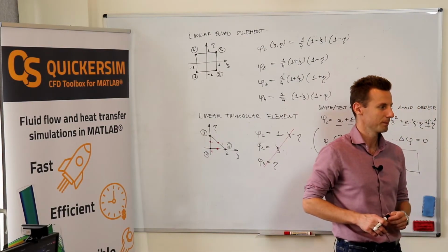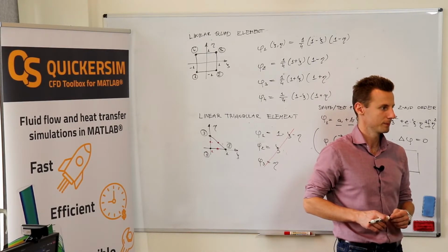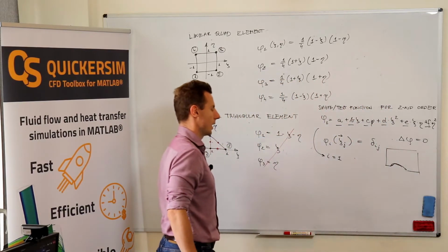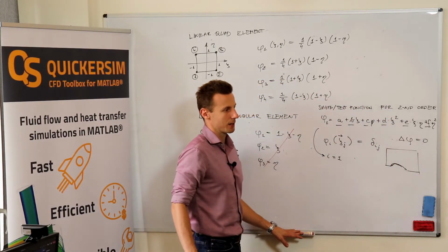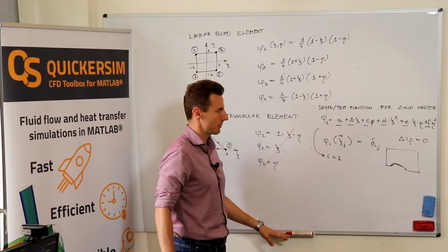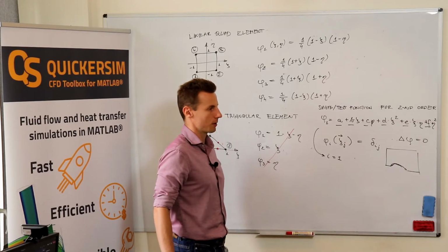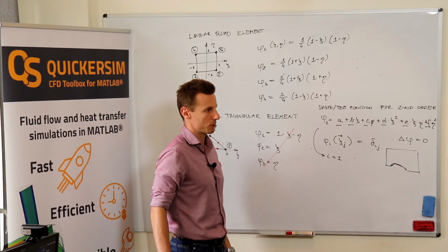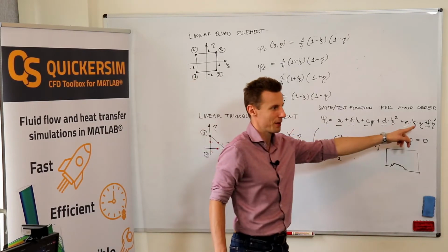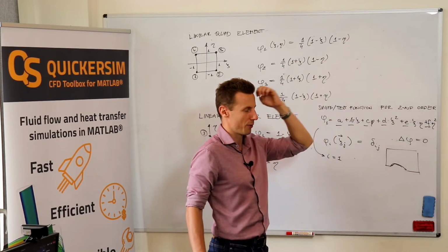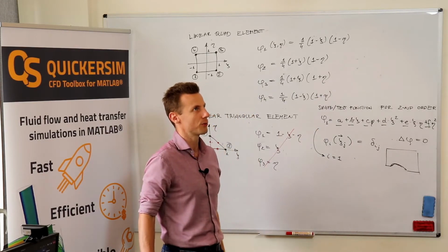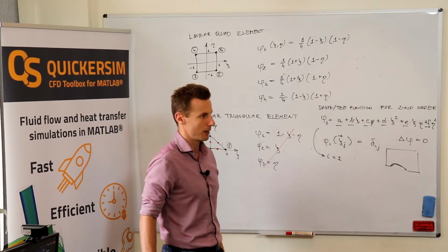One more question. What's the difference between higher order finite element method and spectral methods? Are they the same? Well, I would say finally it's the same. You construct the matrices and the shape functions a bit smarter using the Cartesian product of the one-dimensional functions, because it would be extremely difficult to come up with such a formula for 121 local nodes that you've got in 2D for the 10th order spectral element.